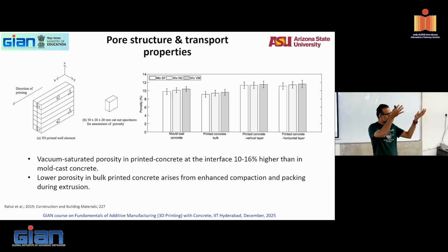And that is why we have transport of moisture and all the other ingredients from the surface, everything going in through diffusion, going through to the level of rebar. So porosity and pore connectivity are the ones that are important. Porosity you can easily measure. Pore connectivity we always had difficulty measuring, but right now with electrical impedance measurements, you can actually quantify pore connectivity. You can also do beautiful imaging methods to look at the connectivity of pores and start quantifying it.